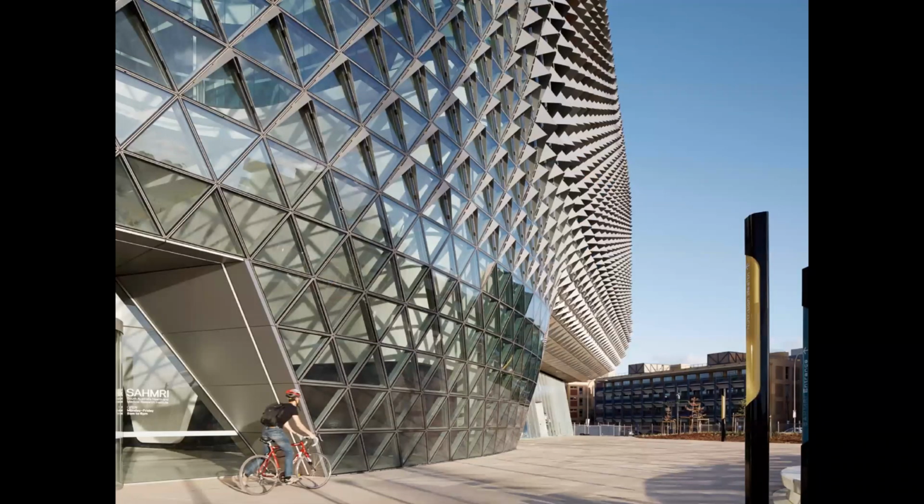Right, and so you can see at the pedestrian level, they almost disappear, right? They do disappear at the very end, right? They start to push back until they disappear and become so thin you don't even see them, to open up at the pedestrian level and where you have shading anyway, right? And so again, this isn't a one size fits all approach, where I'm going to make one shading component that can be repeated all over the place, right? It's an acknowledgement that maybe the south side and the north side and the east side and the west sides of the buildings and the tops versus the bottoms can all use the same sort of geometry, sort of vocabulary, but at the same time, they're all different, right?